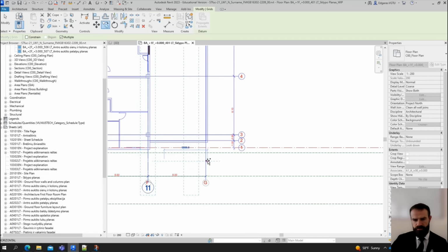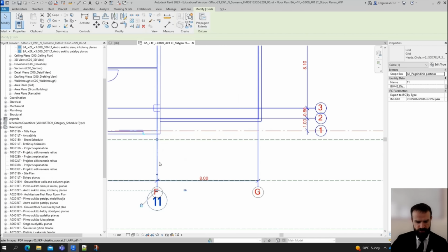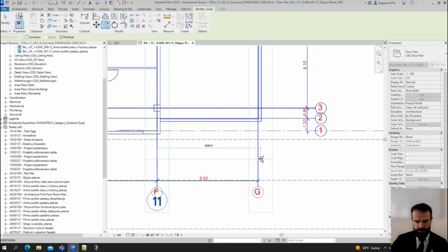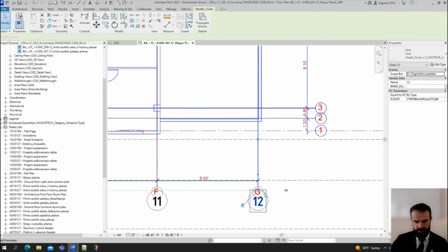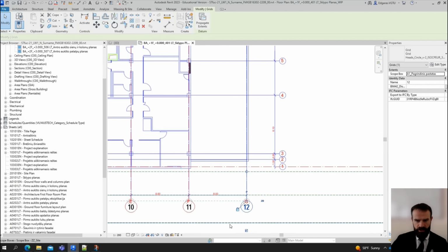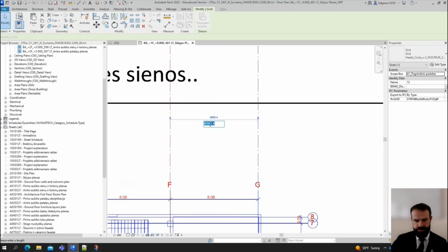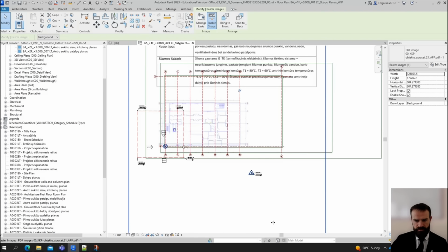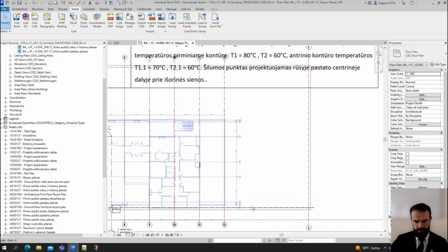If you snap directly to the PDF file, you can get maybe not so precise measurements. If I just copy and snap to the PDF file, so if I select my grid line and activate dimensions, you can see it's 8 meters, 0.4 millimeters. So in this case, it should end by 0, 0. So it's important to have a nice representation, or just retype all the numbers so you get the nice information.